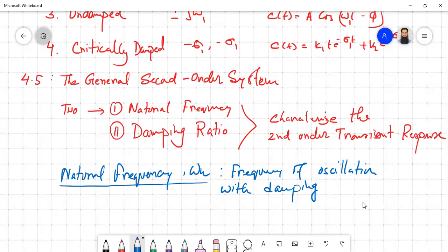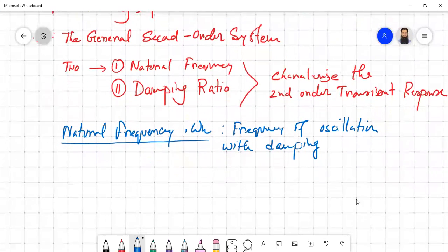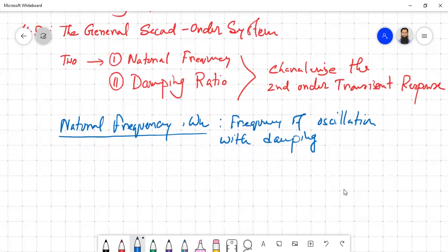Okay, so maybe you can consider the RLC circuit. If somehow the resistance is shorted, then energy will be just transforming from inductor to capacitor, capacitor to inductor. So it will create a pure oscillation. The resistor acts like a component where the energy is being absorbed. So if there is any absorption, then energy will not keep transforming between the capacitor and the inductor. For that, the capacitor and the inductor should also have no resistance at all. Okay, so this is your natural frequency, the straightforward one.